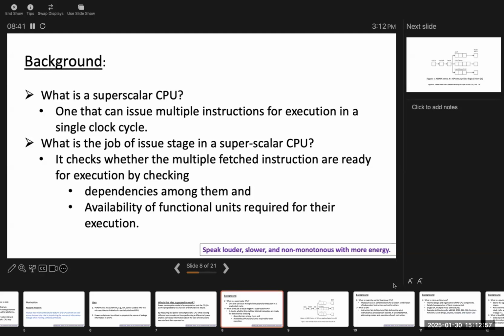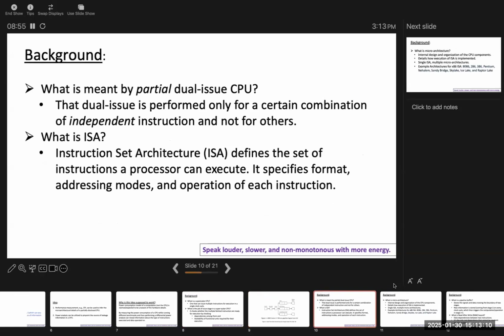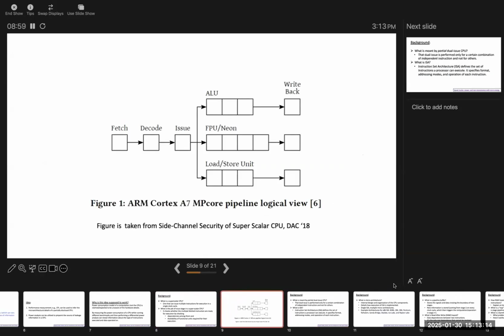Why? This is one of the questions they wanted to answer in this paper by looking at the CPI indexing of the micro benchmarks. I will explain what CPI is later. But this is the information they had available, and it doesn't give greater details about the architecture. This is just a logical figure. You have fetch, decode, issue, but there is no information available. Yes, they said it is dual issue, but in what scenarios you can do the dual issue and in what other scenarios you cannot. Second, yes, they show here that there are pipelines, but how many pipeline stages there are, they don't know.